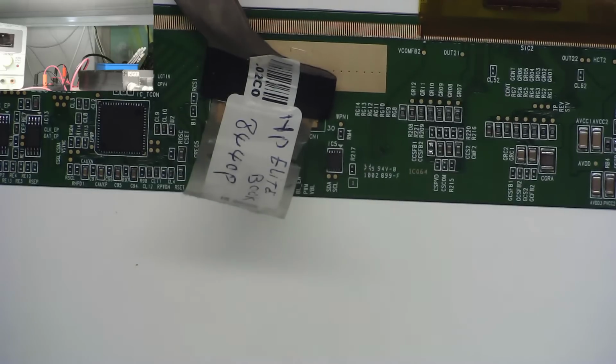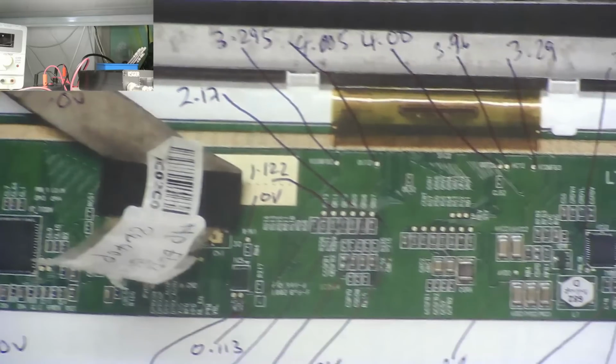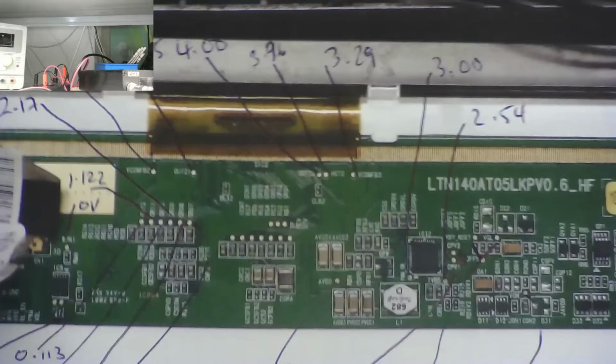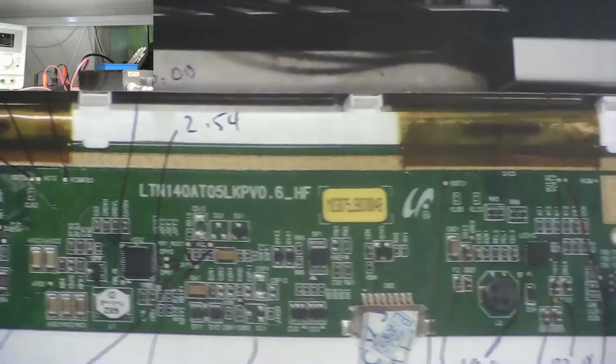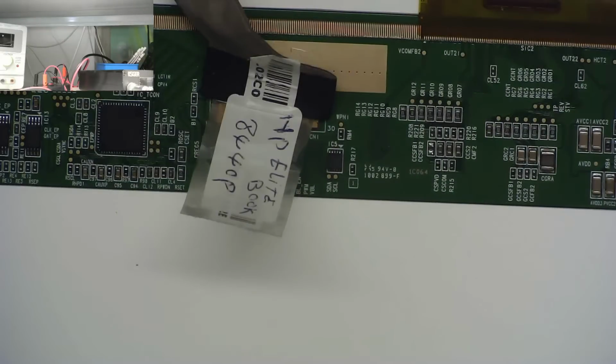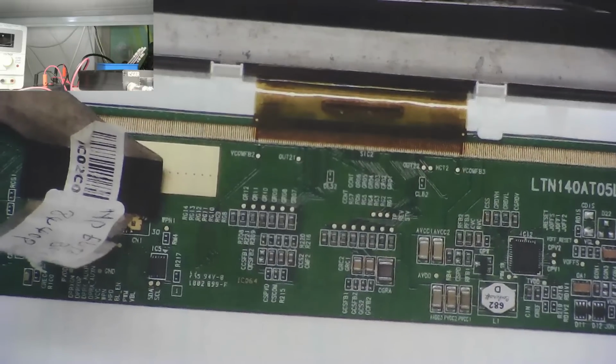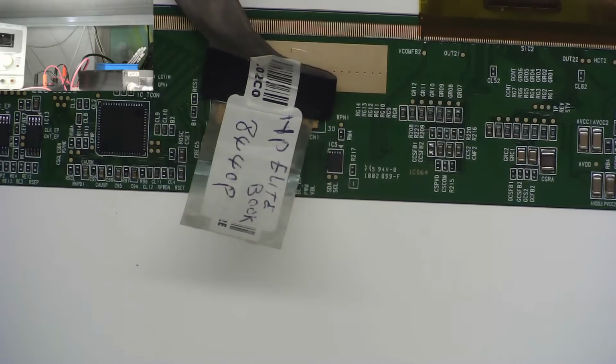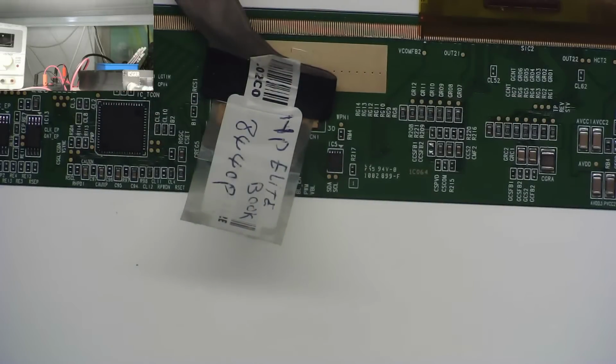Okay guys, so basically I took a photograph and printed a picture of the circuit board, and I went across all the test points on the working one, or the one that gives a picture, although it's a bad picture, bad screen, and I made a note of all the voltages on all the test points. I then took a photograph of the board off the other one. Well, no, it's the same photograph, just printed it twice. And I went all the way across the one that doesn't give a picture, just the backlight, and checked all the voltages on that one. And basically, the truth be known, they're the same.